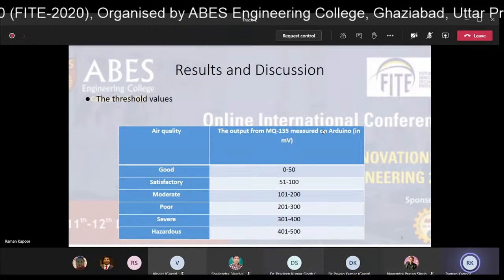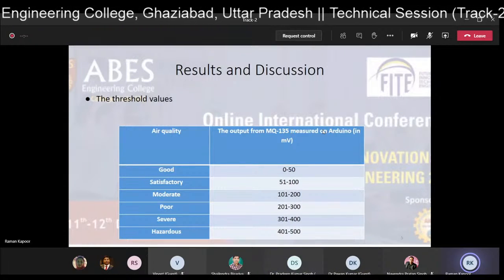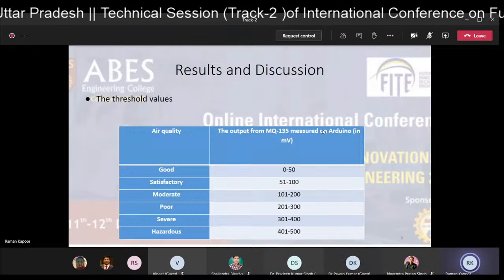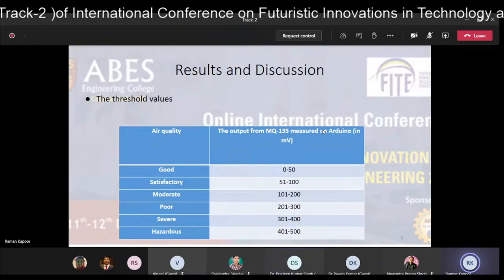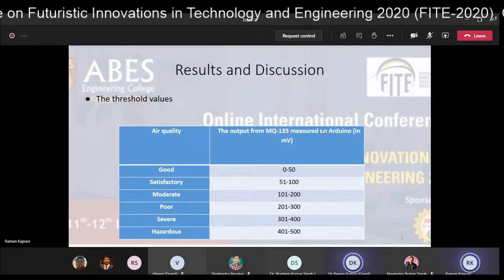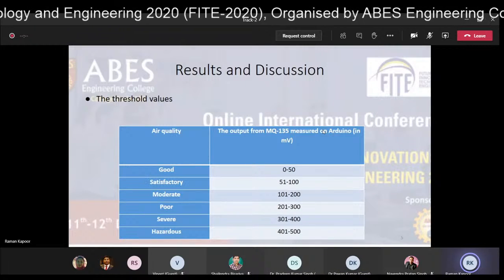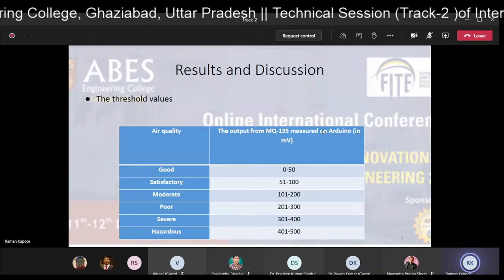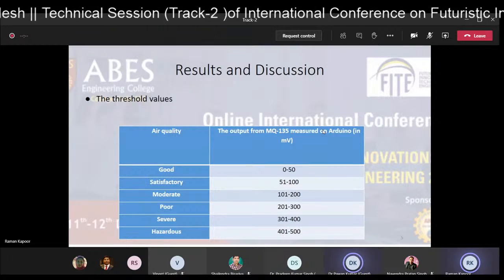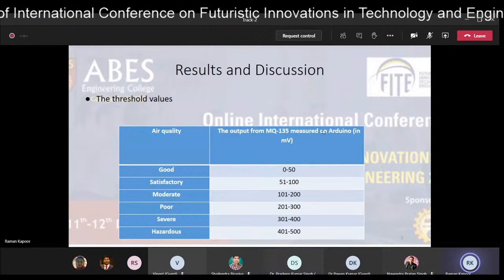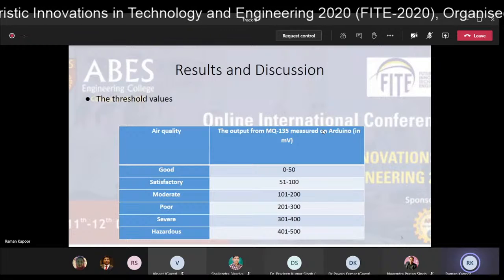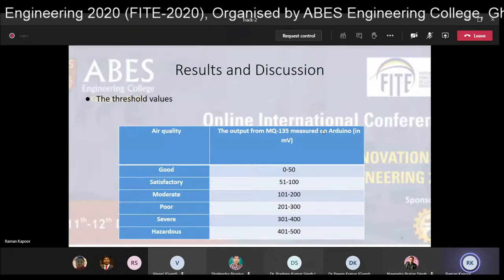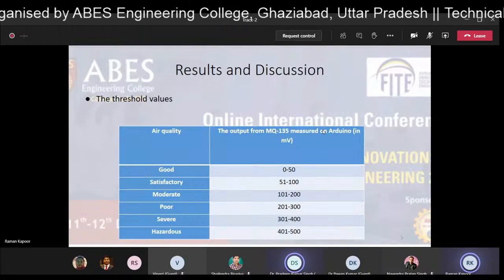So instead of going inside that chemical reaction, you have to rely on the output of the sensor. Then you can design your embedded system. The same sensor will produce different voltages in a pure environment and a highly polluted environment.